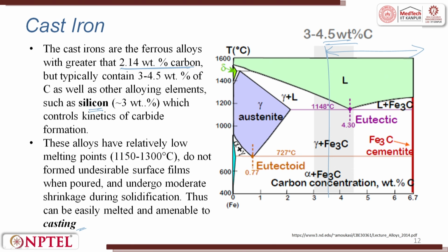When you go to very high temperatures and then come back to room temperature, the material is prone to oxidation. For example, aluminum always forms a thin film on top. Just a fresh aluminum, when you scratch it, it immediately oxidizes. But cast iron does not oxidize, and you can take it to high temperature and pour it inside a confined space. It does shrink, but not so much. So, it tries to replicate whatever shape we have in the die.